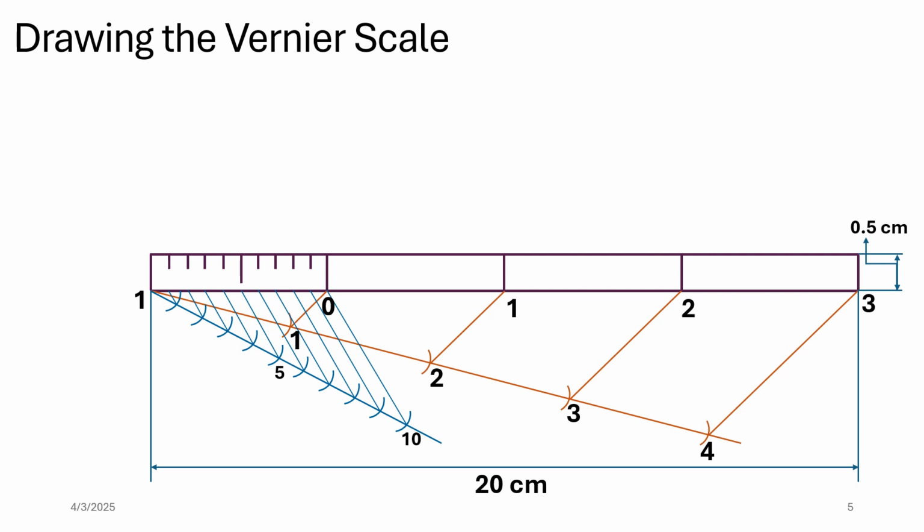Now because we have to divide other parts also into the same number of parts, we can transfer these points with our compass on these divisions. So we have these divisions on this part, and we have transferred this with our compass. So these parts are also divided into 10 equal parts.